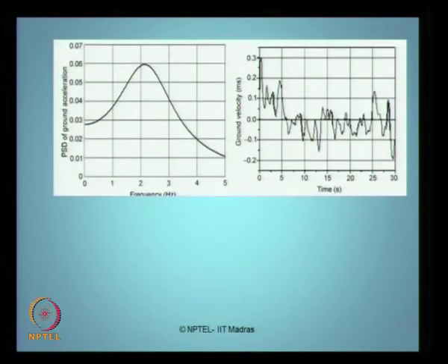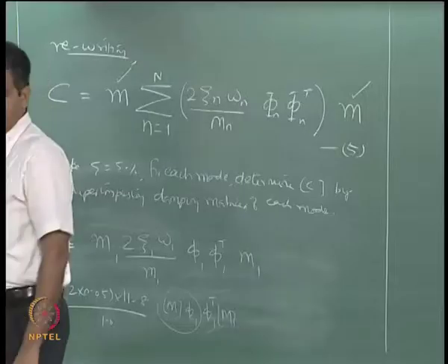So this is my signal. This is my power spectral density of the ground acceleration, which matches exactly with what we had in the specific geographic location in the close vicinity of the Mars TLP in the Gulf of Mexico. The right side is the ground velocity time history. This has been used because I need the ground velocity time history to compute my relative displacement in f of t, because of which my delta T will change in my tethers.